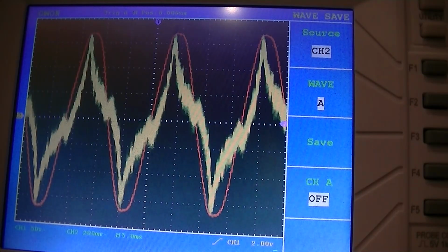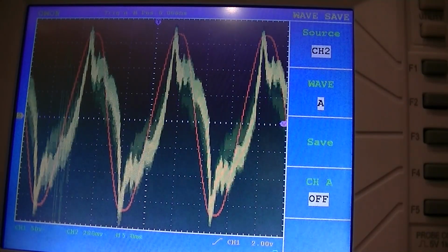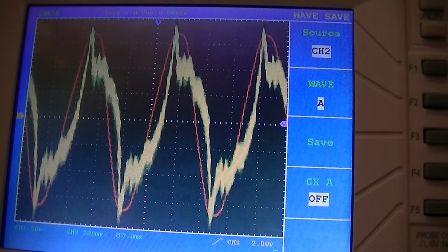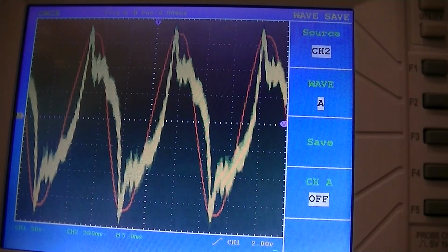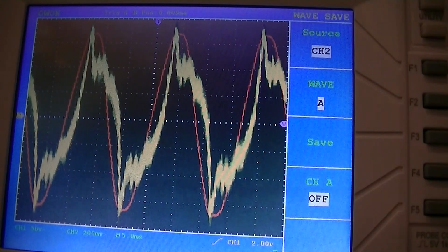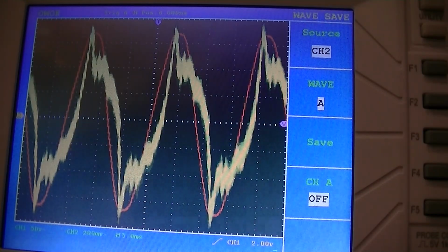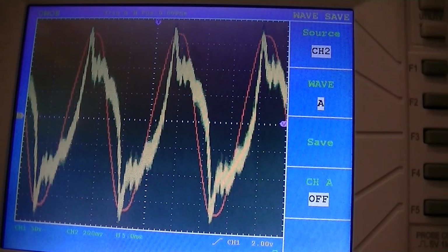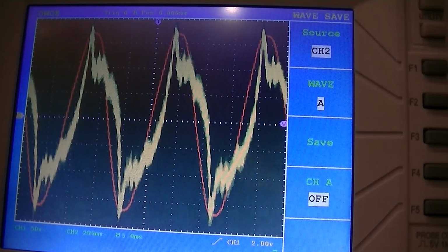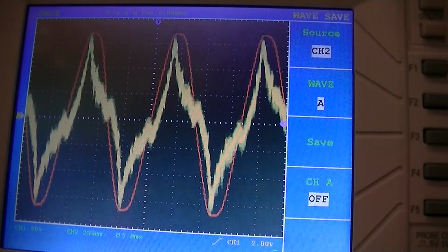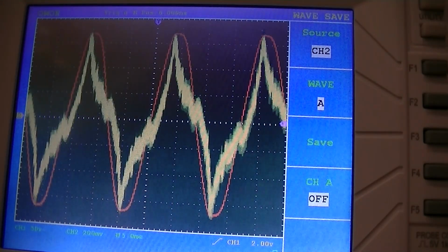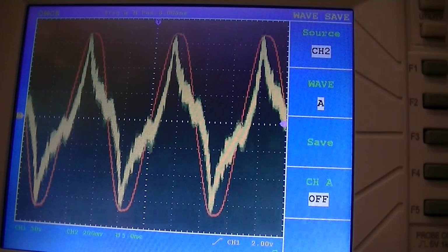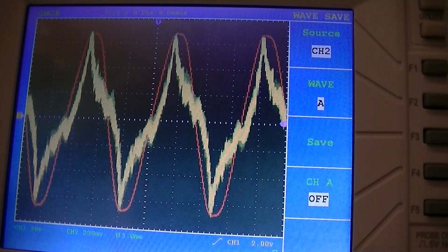I'm now going to switch on the capacitors on live 2. Now you'll notice that the waveform is distorted, and it moved over to the right this time. So that's the difference between putting capacitance on one phase or the other phase. It depends on which way it shifts the waveform. So I'm going to turn this one off, and we'll see it go back to the original waveform. Okay. So we have the original 9 capacitors on the system right now that are at the fuse board.